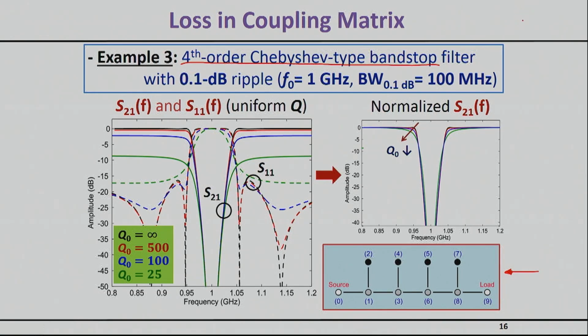But what is interesting to note here is that now your insertion loss is of course penalized in the out of band. So here is, for example, the insertion loss of the 25 out of band, and here's the insertion loss of 100 out of band. So you have to worry about this part. In addition to that, you will worry about loss of selectivity, and this happens towards the edges of that filter. Now, even though it is not shown explicitly in this graph, this will also limit the maximum attenuation that you will be able to get. So the maximum attenuation will also be penalized in those types of filters.